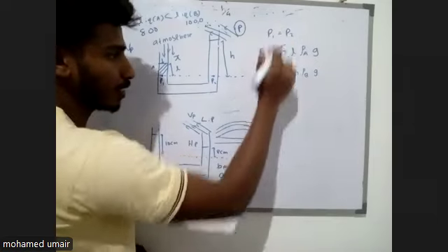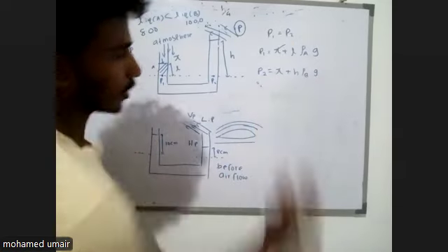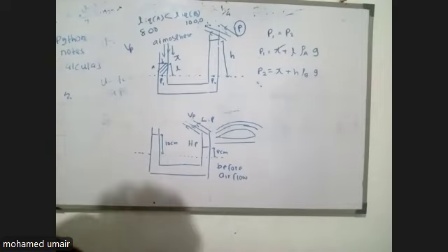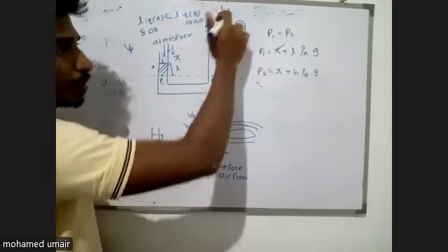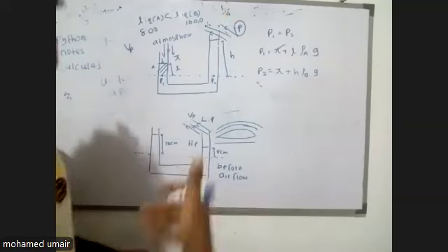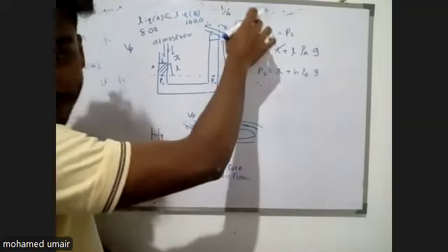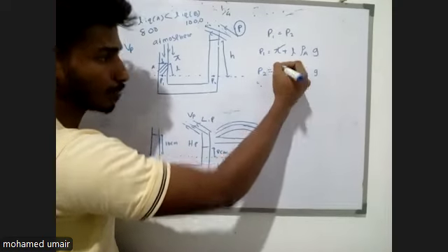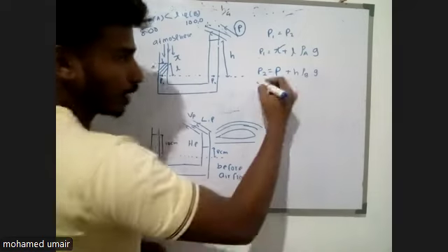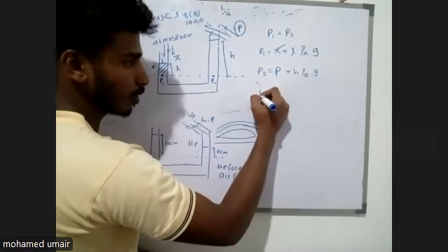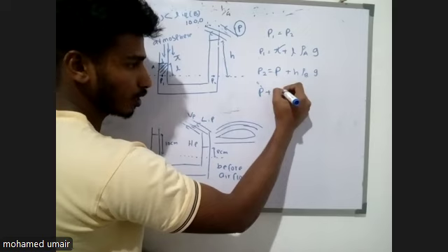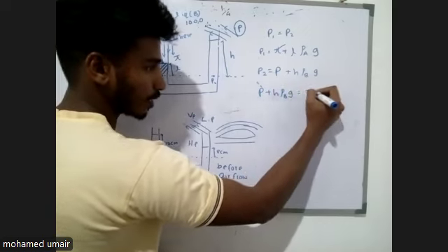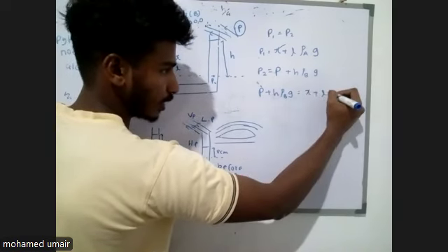Now see here, with the flow, I can also make mistakes. I have taken the pressure as Pi, even though it's a U-tube question, the pressure is different, okay? It's P. So I'll just include P. Now when I equate both of them, P plus H rho B g is equal to Pi plus L rho A g.